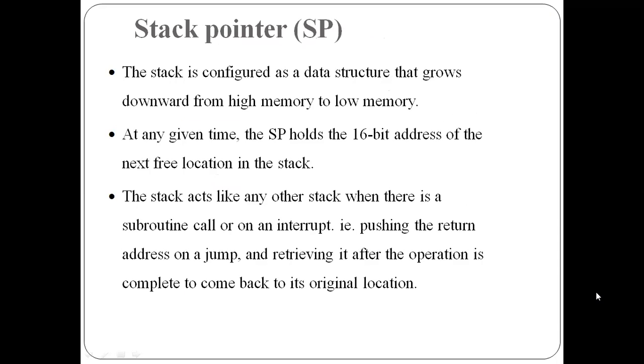Stack pointer: a stack is configured as a data structure that grows downward from high memory to low memory. At any given time, the SP, that is the stack pointer, holds the 16-bit address of the next free location in the stack. The stack acts like any other stack when there is a subroutine call or an interrupt, that is pushing the return address on a jump and retrieving it after the operation is complete to come back to its original location.